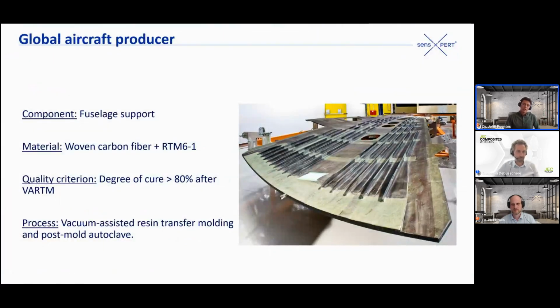Now, the image that you see here, of course, is not a part of our customers' inventory, but this is just to give you an example of any composite part that most of you might be producing. You see the complexity. There are different fibers, fiberglass. You have carbon fiber, and with this carbon fiber, you have different orientations within the part to make sure that the stresses that this is going to withstand are fulfilled. And also, most likely, this is going to be an epoxy system.